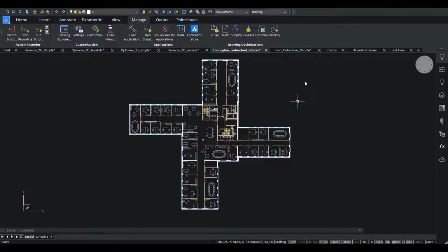Moving on to the next drawing optimization tool, Overkill is present to remove duplicate entities. This is a tool that exists already for quite some time, and the goal of the command is to analyze a drawing and to find, for instance, overlapping lines. Since we like the idea of the command, we have extended the functionality with a new mode to also automatically look for duplicate block definitions.